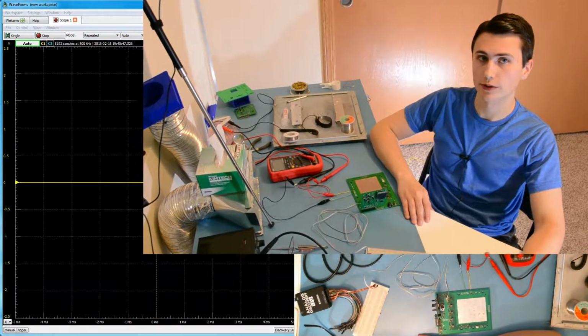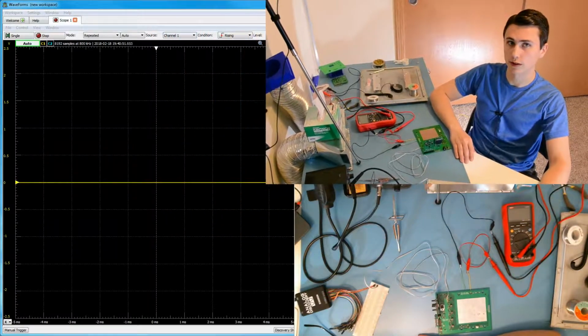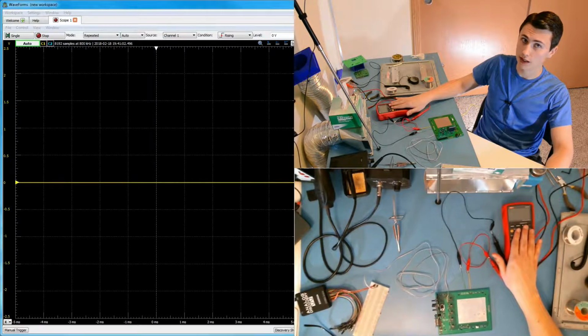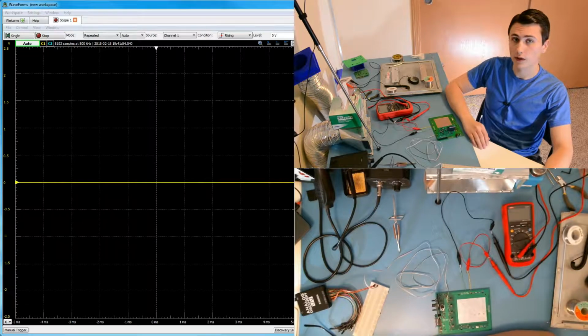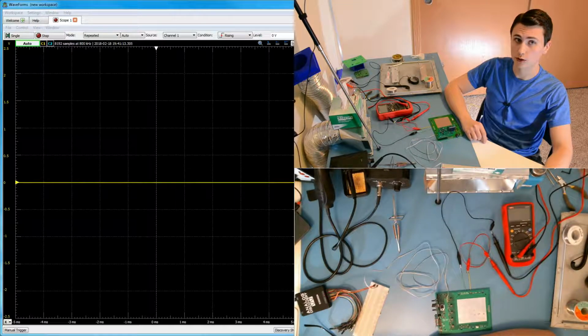Measuring current is kind of a tricky thing since one needs to break the circuit to properly measure current. That's why I added the 0603 resistor pads across one LED in each loop. Since the voltage dropped across the current shunt in my multimeter will be much less than the forward voltage of the LED, we know that nearly 100% of the current will be flowing through the multimeter. If you don't know that, then you should check out my video that talks about how to control the brightness of an LED. Hopefully that will help to clear things up.